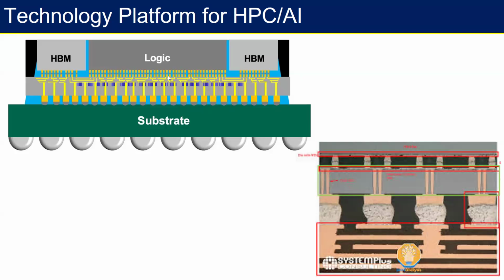And then you see that they are connecting these wires which are coming from the logic and memory, right? So what are these wires? Obviously here there is only one gold standard, and that is copper, right? So if there is wiring, we follow it all the way from the die, which I will go into briefly in the next slide. But here you see these are copper wires, right? Copper wires passing through your silicon substrate, copper wires passing through these connections. So the yellow is the copper wires, and when these copper wires are passing through the silicon, they are what we call TSVs, or through silicon vias, right?